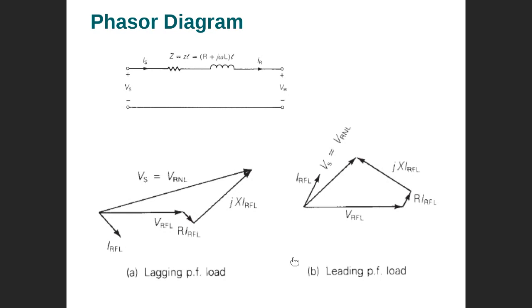But if it's unity, that will be okay. But 0.99, 0.98 is good. So we don't prefer leading power factor, but we prefer one per unit, that is unity power factor. That will be okay. So that's maybe the idea. But too much lagging is not good. Okay. So 0.87 maybe